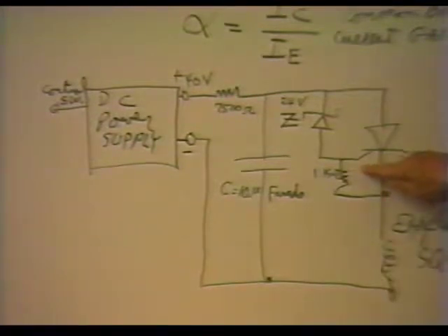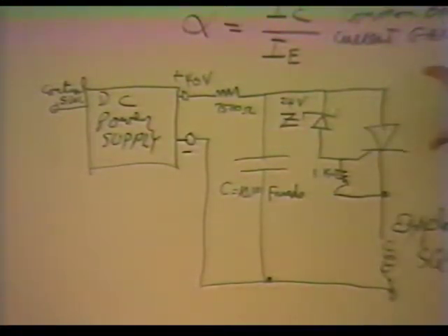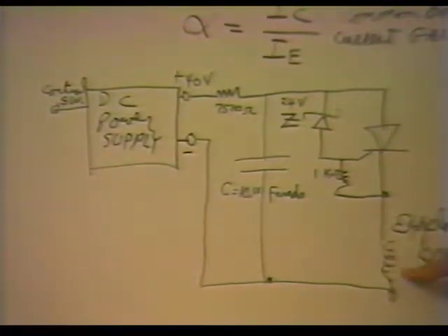The current turns on the SCR, and when the SCR turns on, this capacitor discharges through the SCR. It's a switch. It was off. When the gate turns it on, it becomes a very low path. The current goes through, lights up the bridge wire, fires the squib, and the fins open on the weapon. And it happens very quickly. It's a very closely timed circuit. Now, later on, I'll tell you why we used 7,500 ohms in here, and we'll get into some of the other operations.